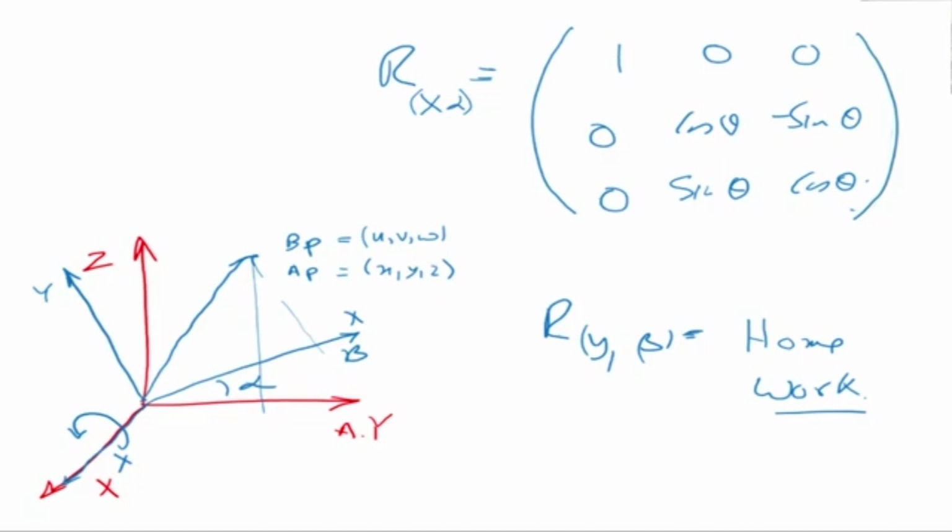But if you rotate twice, for example, I rotate about the z axis, then I rotate about the x axis, okay, then what will be the compound rotation matrix? That's one question. The second question is, suppose I rotate about the fixed frame once, okay, but the second time I rotate about the rotated frame, then what happens?